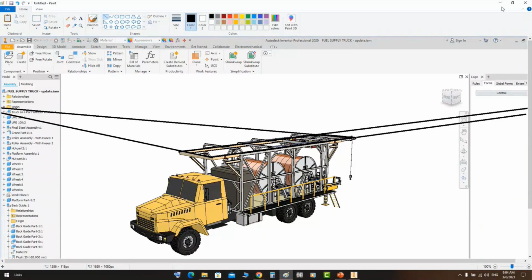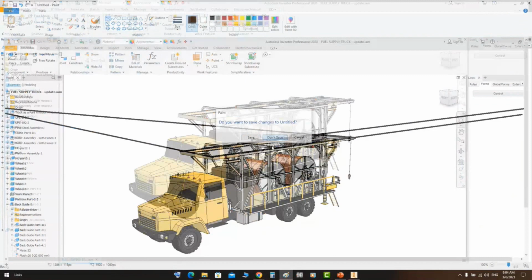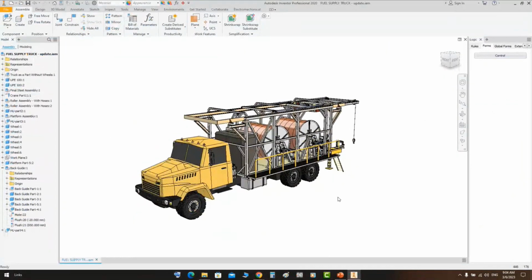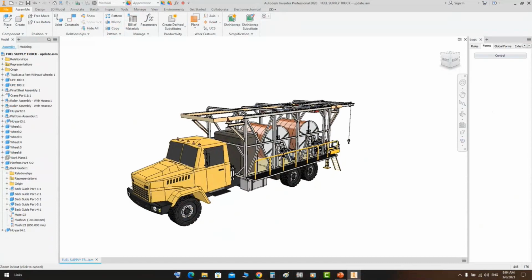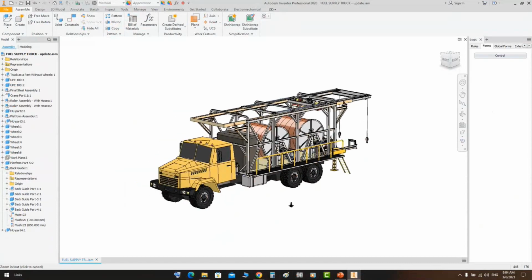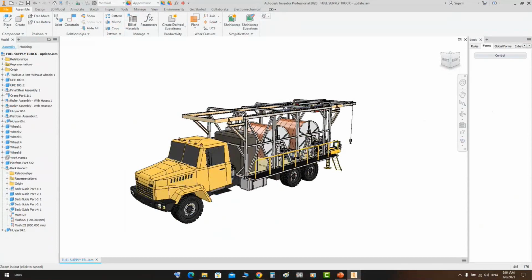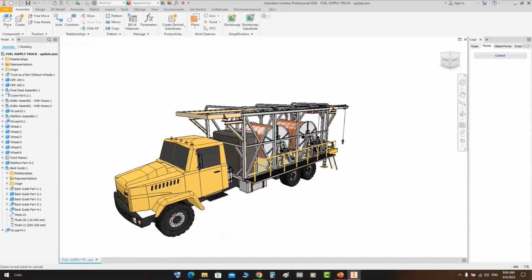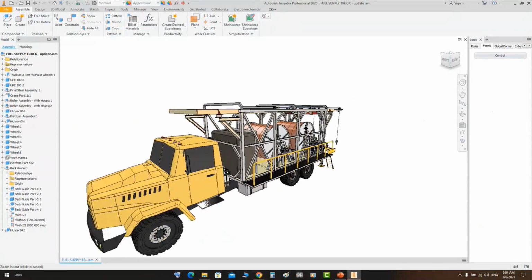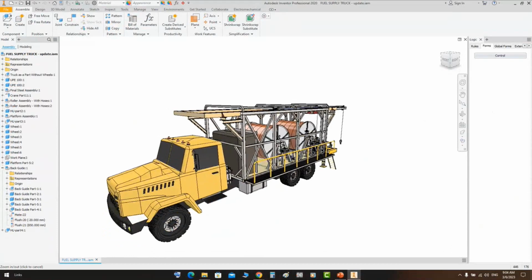Okay, you can change the focus of the perspective view. You can change the end point by clicking Control Shift and F3, and you can change the end point of the isometric or perspective view.